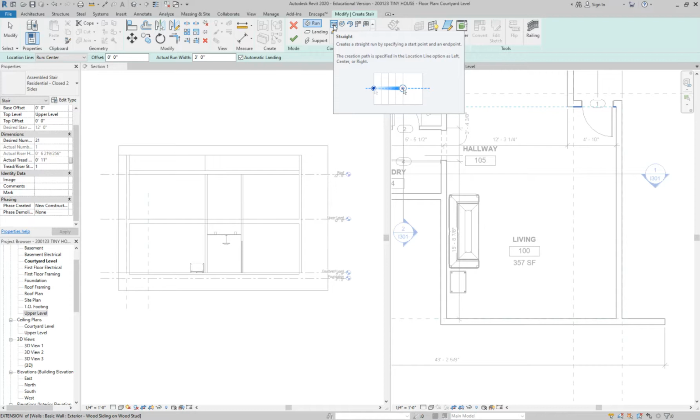Similar to the roofs, it'll do everything automatically. So this is the way stairs work when you're working in Revit. You'll click on the stair you want, and I'm going to use the straight run as an example. And using your sketch tools, you just start drawing a line. And then Revit knows that along this line is where the stairs go. And you can see that somewhere at the end, there will be a note that says like 8 risers created, blank remaining.